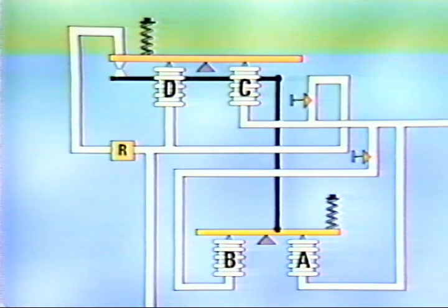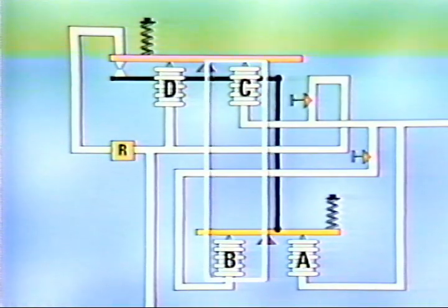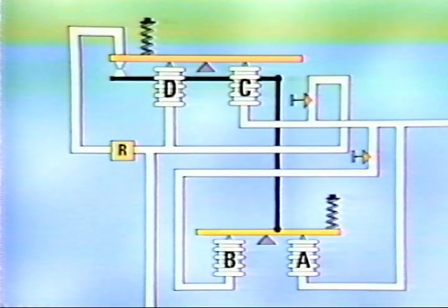If input changes, the B and C bellows act on the 2 beams to move the flapper and nozzle closer together. This boosts the output, so the B and C bellows are initially the rate bellows. Then, after the input stops changing, the C bellows becomes the reset bellows.